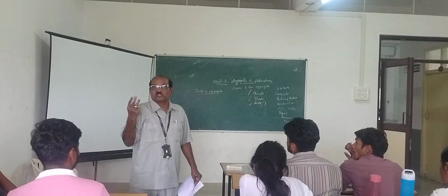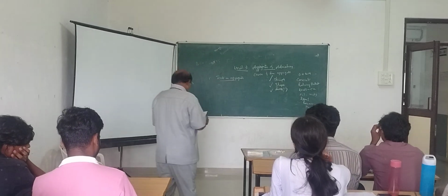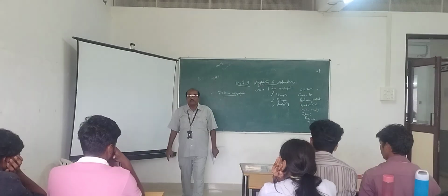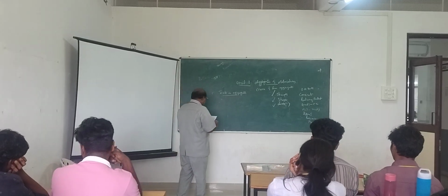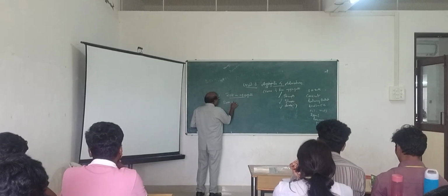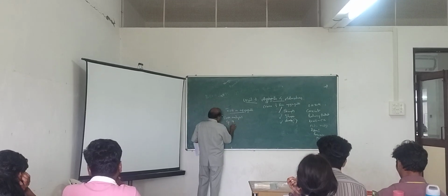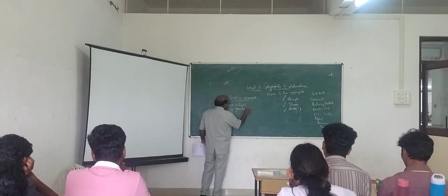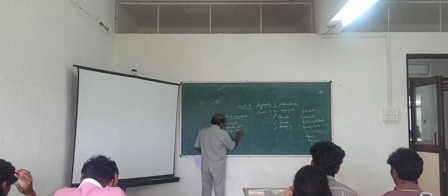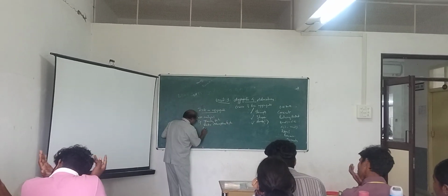I said only 3 questions. That means this is one of the 3 questions. That means you must study. So, testing is very important to know the quality of aggregates. For that, there are many tests available. What are those tests? Sieve analysis, specific gravity test, then water absorption test, then aggregate crushing value test,